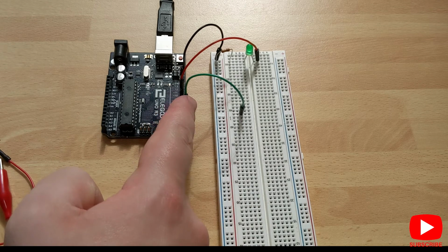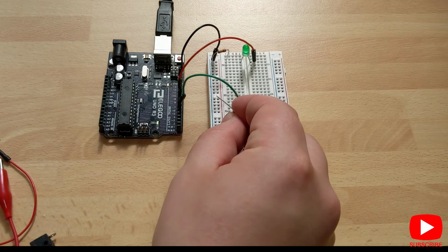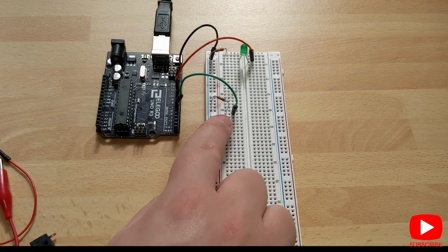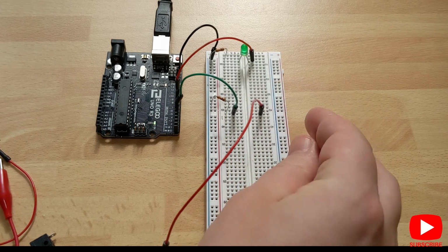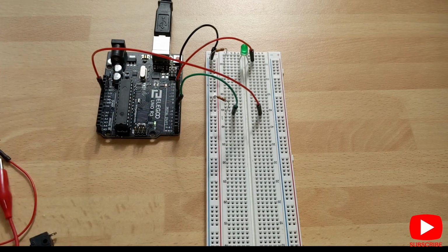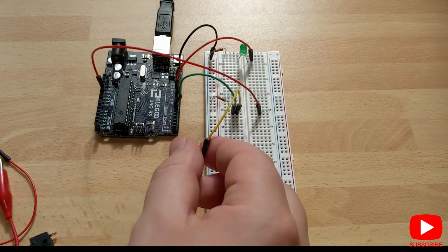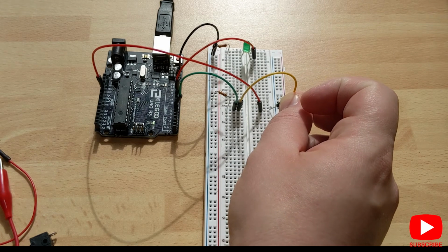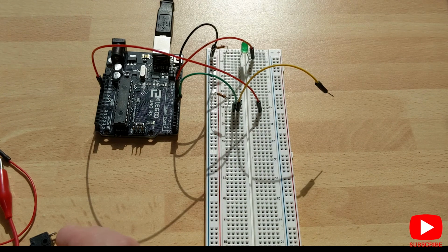So we've got a lead coming out of pin 6 into the board here, so this would normally be our button here, but we're going to put this 10k ohm resistor between pin 6 and ground. We've already got a ground rail running here, and then to simulate our button, I'm just going to pop this on this side here, and we're going to pop that into the 5 volt rail, this one. And I'm going to pop this yellow cable in here. Now, when I plug this yellow cable into this same row that's on 5 volts, that's just going to simulate me pressing the button. So in normal circumstances, I just have a button in between here, but I don't have that. I'm just going to use this wee cable to press the button on and off. I hope that makes sense.